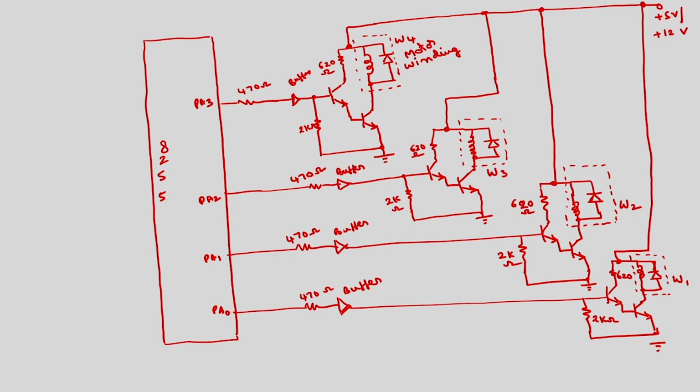So, what will be the control word corresponding to this? I am using only port A. I have to program it as an output port. In order to program all the ports as output ports, 80H is the control word. Okay. So, if I want to write the program here, the procedure is: